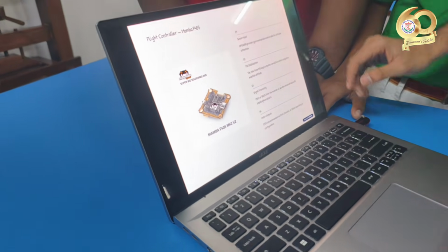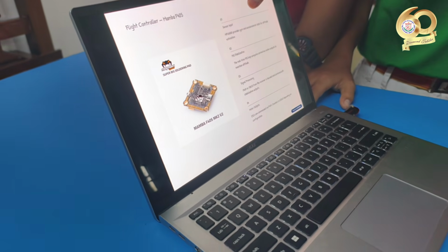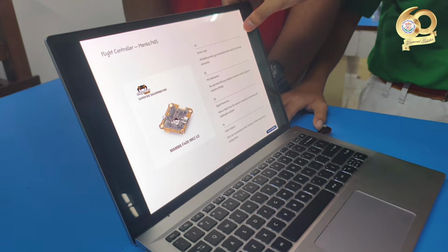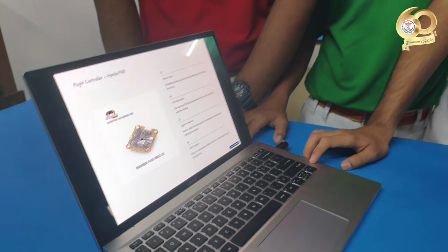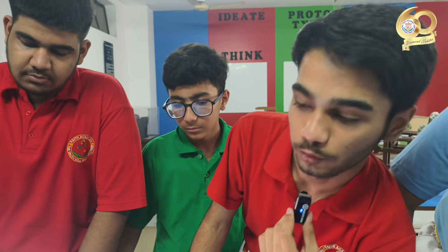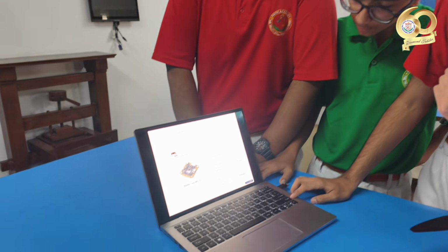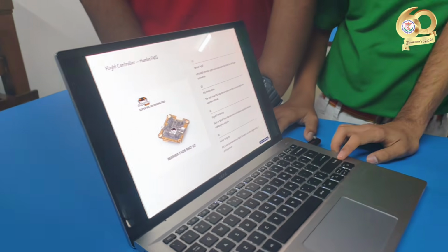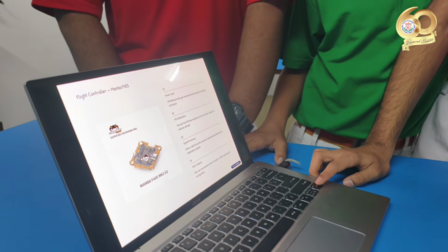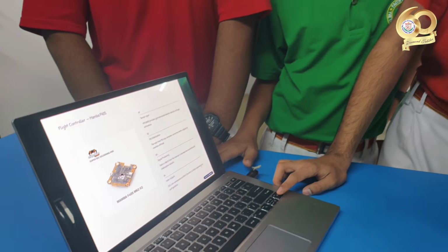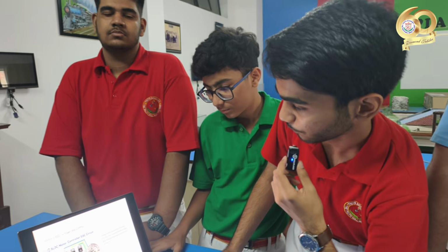It has four main features. Sensor input: the MPU 6050 provides gyro and accelerometer data for the altitude estimation. The PID stabilization: it's the real-time PID which manages the speed of the motors. Signal processing: it takes the S-bus signal from the receiver, which was coming from the transmitter, and gives it to the flight controller in a readable manner which it can easily read.